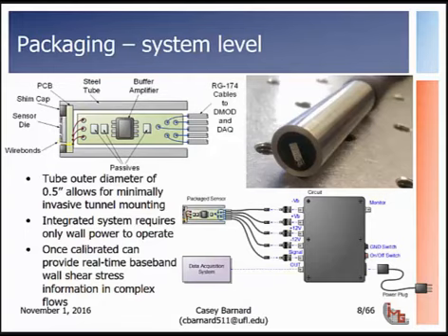The tube itself is 1/2 inch diameter, 2 inches long, stainless steel. Inside is a buffer amplifier. Co-location of this amplifier right behind the die allows us to separate the electronics much further back without any significant signal degradation from the high output impedance device.